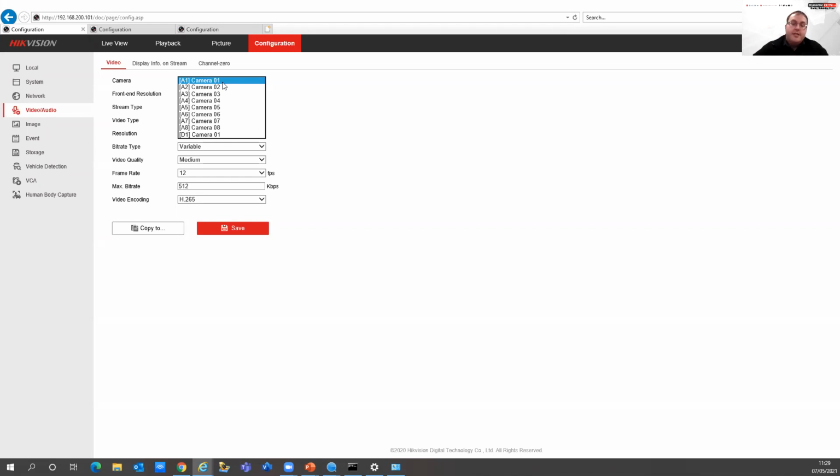If there isn't a lot of motion on screen and it's not in a high traffic area, but the frame rates and bit rates are set quite high, it's just wasting the storage capabilities of the machine itself. So it's best to reduce those to make sure that they're the right fit for the actual site, and you'd be able to achieve the most amount of storage you can while still retaining a good enough image for where the system is mounted.